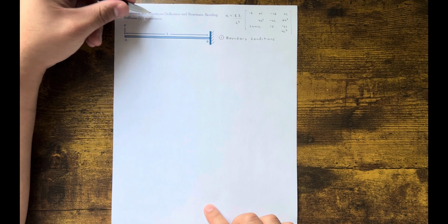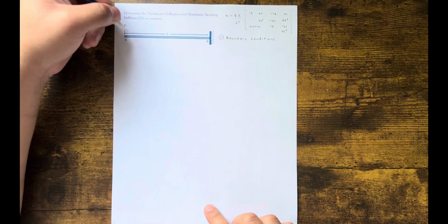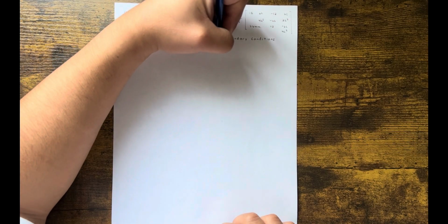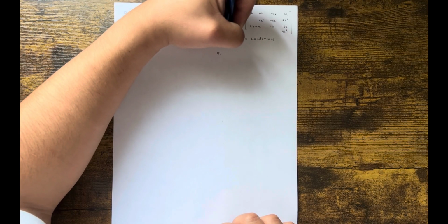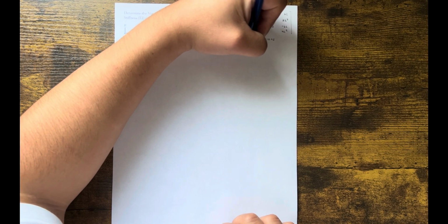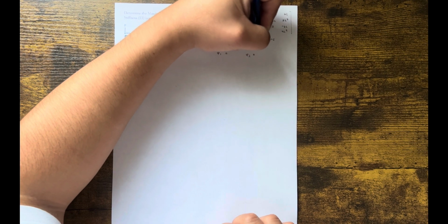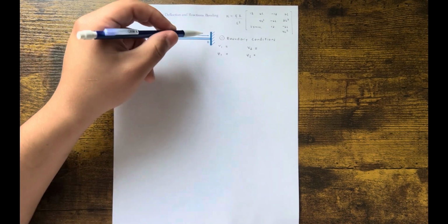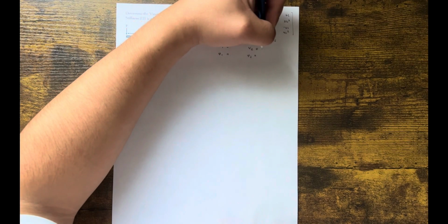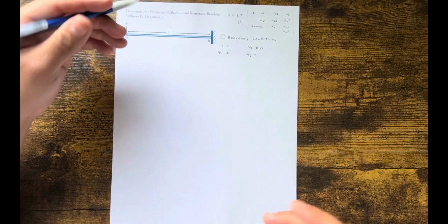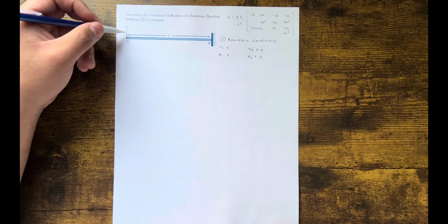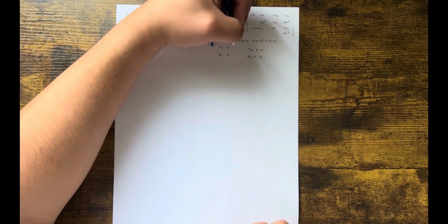So max deflection is gonna occur at this location. Let's call them nodes 1 and 2. Nodes 1 and 2 are going to deflect and rotate at a certain value, right? Node 2, for sure, right here, node B, that's fixed. So that's not going anywhere. That's going to be 0 in the y direction, and then it's not going to rotate, so that's also 0. V1 is going to rotate some value and displace some value, and that's what we're looking for.